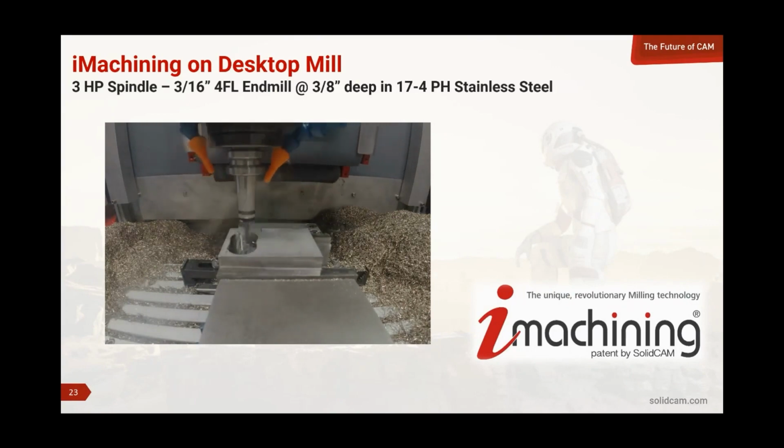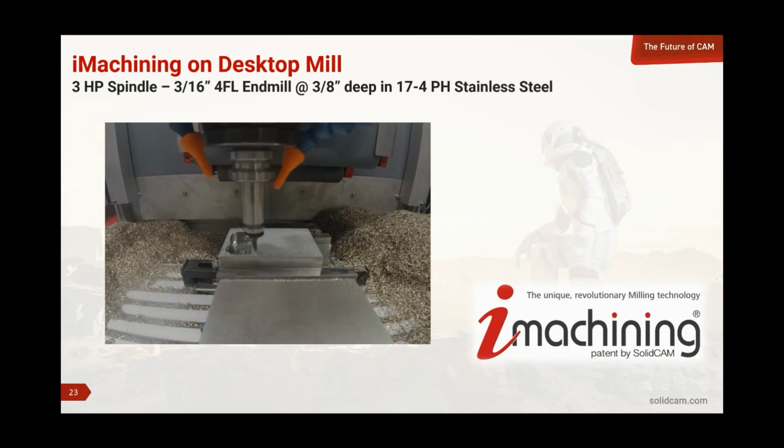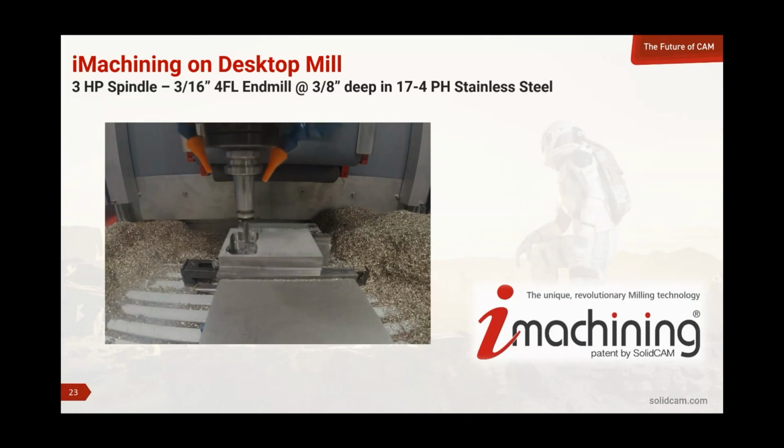And as you can see, we're not wearing this tool out. We're not hurting this tool. This is extreme performance on a 3 horsepower spindle on a desktop CNC mill. And we're cutting it over 2 times diameter depth of cut on this tool in a material that most people would never consider cutting dry because of that thermal characteristic. And yet we're able to do it with iMachining. We're able to do it very fast, very effectively.